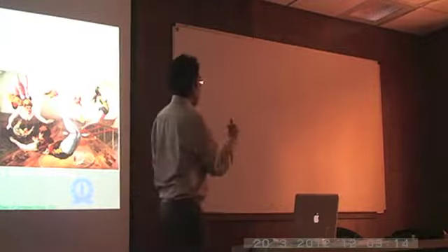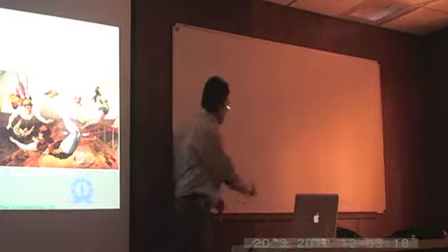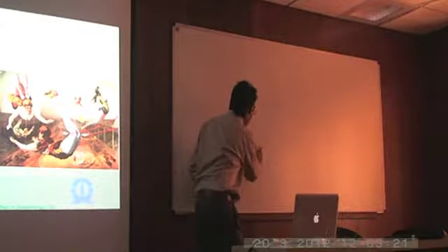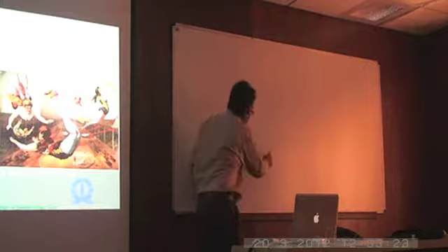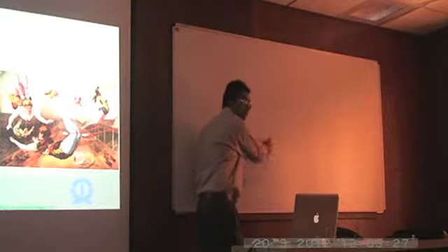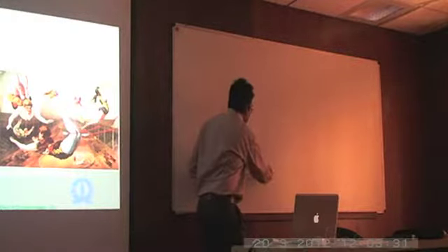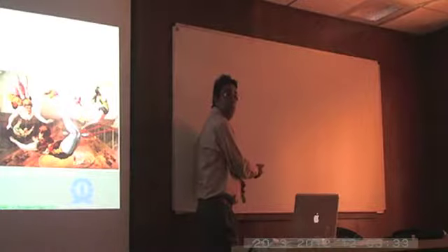Your x3 is of the order of h, and therefore this becomes epsilon by h. So now if you compare these two, you have the same thing in the numerator, but you have a larger number in the denominator here compared to this, because h is small compared to b, the thickness is small compared to the breadth. So what happens is your kappa 2 is going to be much larger.